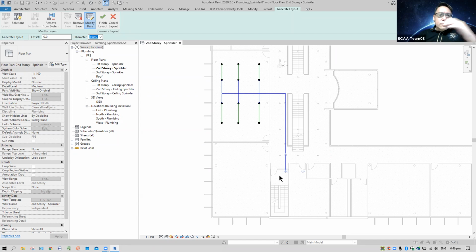Of course here, the piping is biggest, which means pressure drop is low. And this is the supply for the 1st, 2nd, and 3rd floor. When they branch out, the piping will be smaller. So here it's up to you to decide whether you want 150, 120, 100 or whatever, because we have no calculation. If you base it on your tutorial, what is placed there? 150 for the piping. You're going to maintain that, it's fine.